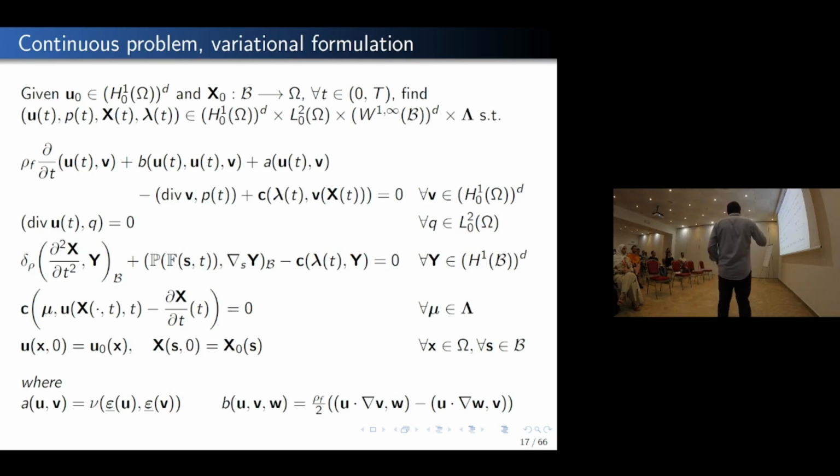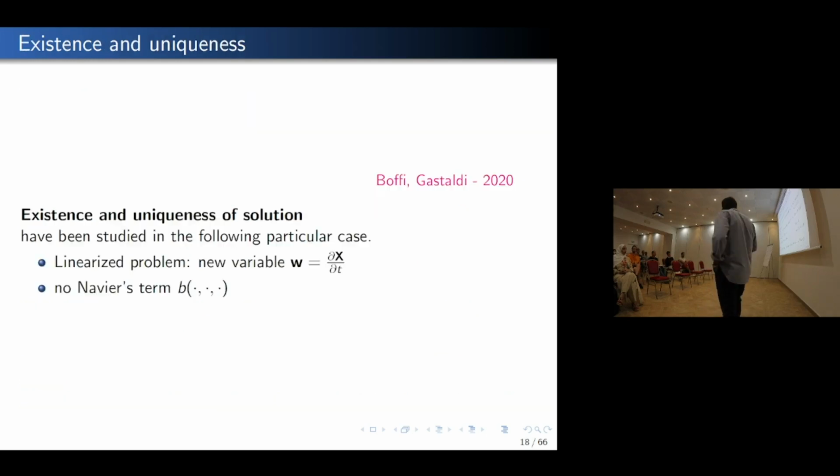Okay, so this is the continuous formulation, and I notice now that if you see here and also here, obviously, C takes as input lambda and v applied to x, because it is important that the coupling condition has to be set in the region occupied by the solid. Okay, so in Omega_s^t. For this reason, we have the velocity test function composed with x.